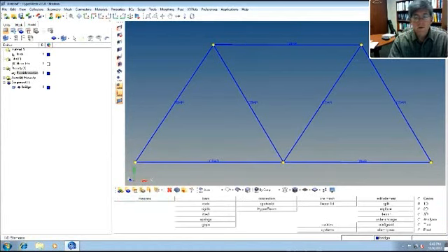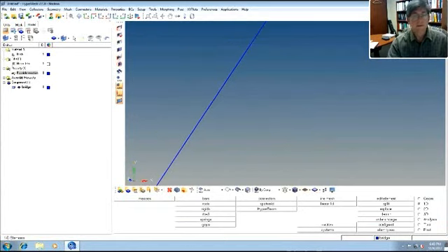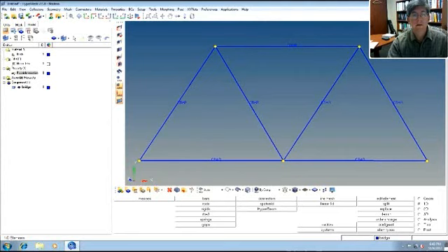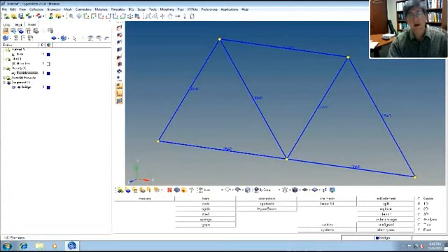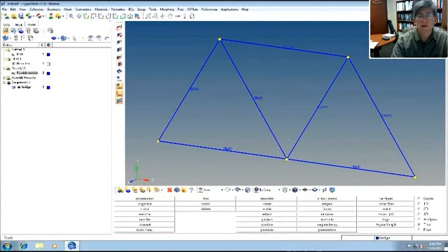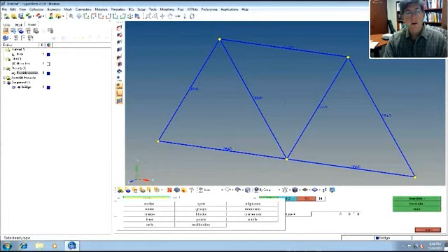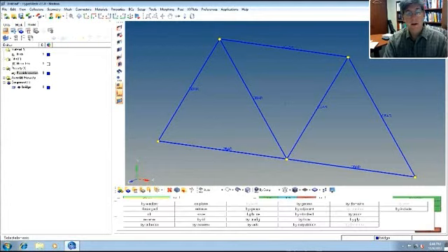Okay. Now we got to make this back frame, right? So we kind of have all these guys. Whoops! I keep zooming in when I need to rotate. All right. So this is the front plane. We need to make the back plane, which is going to be the direct copy of this, but just moved back in Z. So you can do stuff like in tools. Remember I said that allows you to do copying. This is a little weird, and I'll do this quickly. You can stop and go over this a little more slowly if you want, but you just have this one. There's lots of tutorials in Hypermesh to help you do this stuff. So we're going to do translation, and we're going to translate elements. So I'm going to pick all the elements.